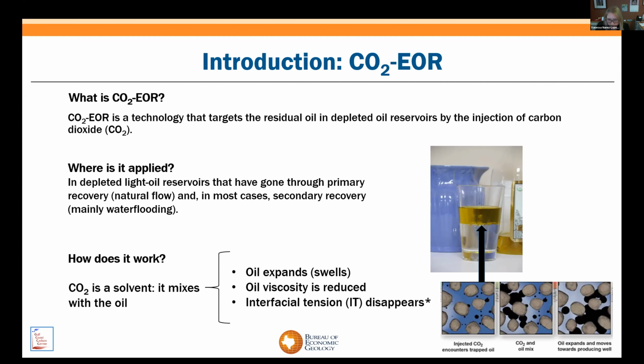If the CO2 and the residual oil are miscible, which happens at pressures above the minimum miscibility pressure, then the CO2 starts to act like a solvent. It's kind of like cleaning the rock in the similar way that a solvent would clean your tools.